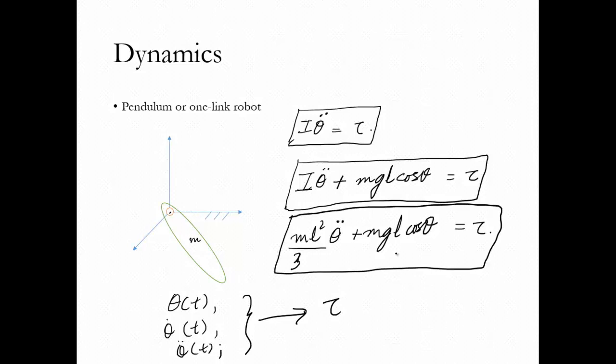With these equations, we can control this single link manipulator to act as per our requirements in terms of control performance, because we have the dynamic model with us. All right, so in rotary systems we have seen that there is a moment of inertia component that comes into play. It's not just the mass as in linear systems; the moment of inertia is very significant.